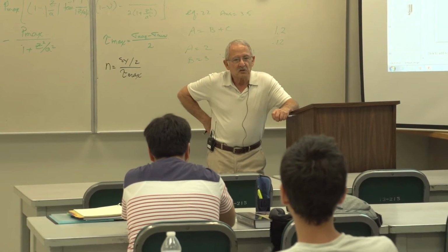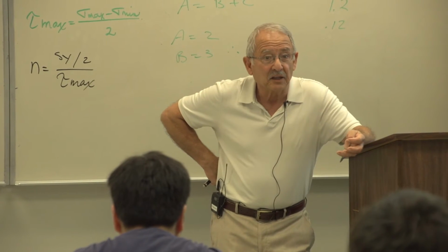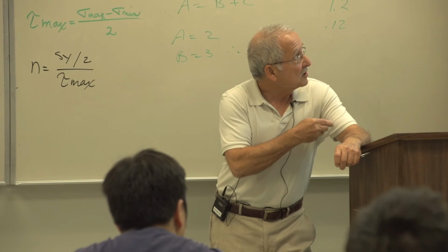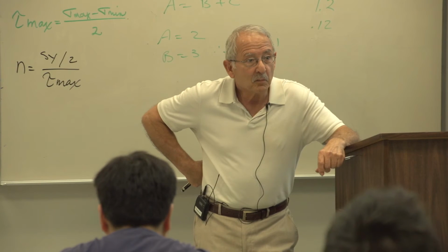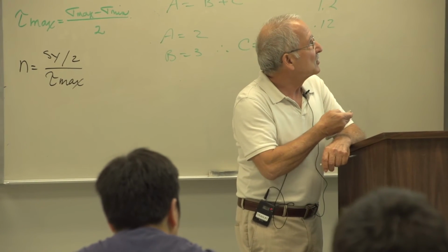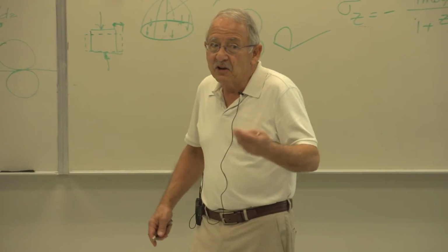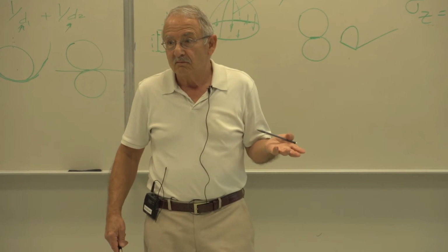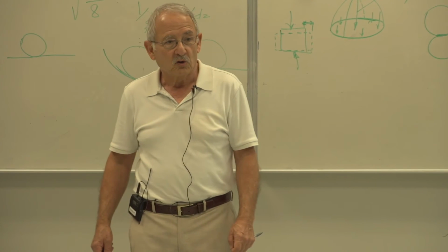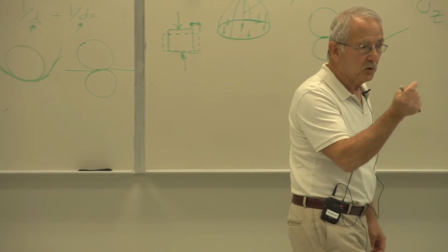In order to calculate the von Mises stress, what do you need? Principal stresses. Agreed? Are these not principal stresses? So you have them. But, for example, for sigma z, what value do you pick? Do you pick the value at z equal to 0? Or some other value? Of course, whatever value you pick for z for sigma z, you should use the same value for the other two stresses as well. In other words, you should be looking at one point. And that one point will have one z coordinate.